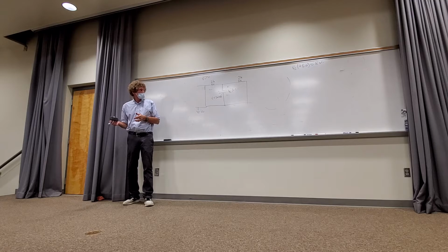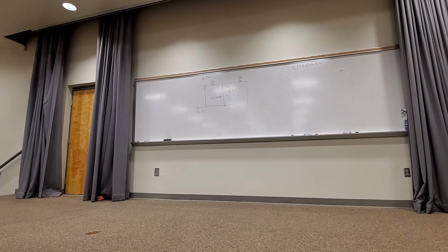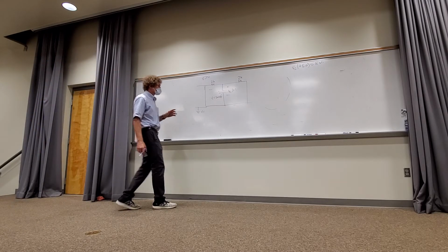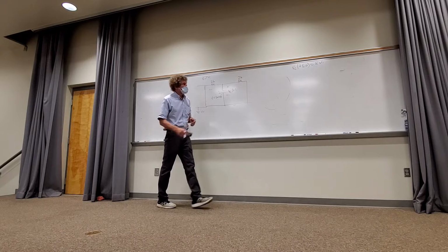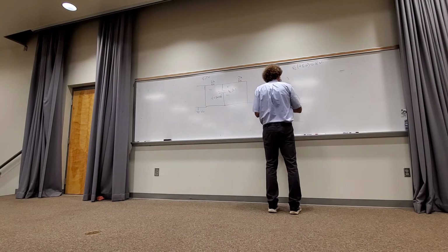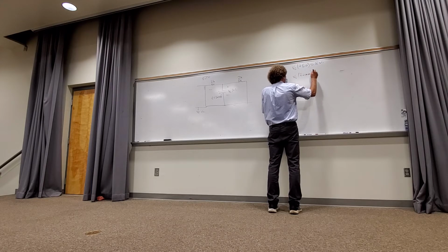Now, what is the voltage across that capacitor going to be at t going to infinity and why? Anyone? 0. Why? You're right. There's nothing going into it. There's no energy source to sustain that voltage. Y'all follow me? There's no power. If there was a battery, maybe it wouldn't, right? But there's nothing left in that circuit to keep that capacitor charged. So if the capacitor can discharge, it will, and it surely can. Y'all see there's 2 resistors there? So now we know VC as t goes to infinity is 0.